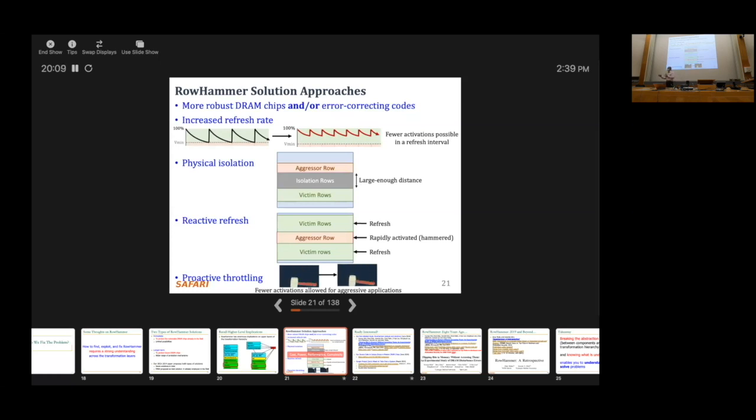Now, people propose moving data around inside the DRAM chip much more efficiently. Like, we have some work on that without going through the memory controller. That can reduce the problem. But again, you're still moving the data around. And moving data around is, in general, one of the most costly things that we do in our systems today. But it's great. I think you guys have proposed a lot of solutions. And this is tricky because every solution has to be evaluated in terms of cost, power, performance, and complexity. And there's no perfect solution to this problem, basically.